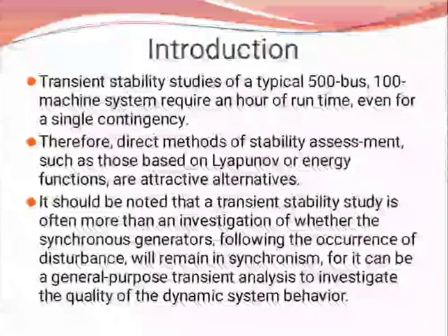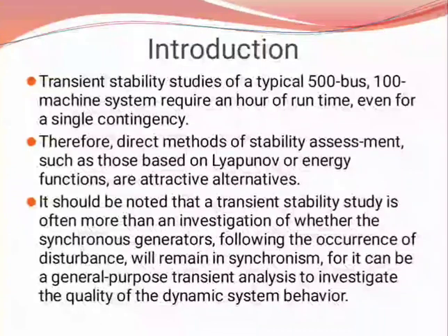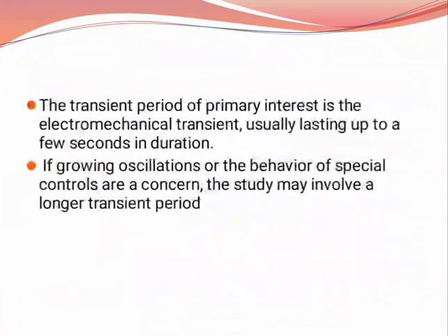Therefore, generally the direct methods of stability assessment, such as Lyapunov or energy functions, are the attractive alternatives for this situation. It should be noted that transient stability study investigates whether the synchronous generators will remain in synchronism following the occurrence of disturbances, so that general purpose transient analysis can investigate the quality of the dynamic system behavior. So this we are going to study in detail.